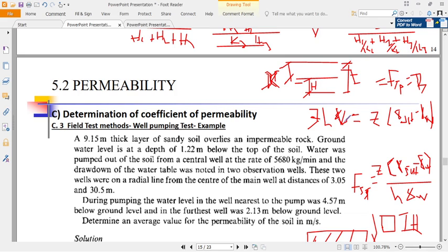There may be a pressure increase, should be equal to Z. Now, which is Z? Z is a function of X plus H. This H is the thickness of the layer which is known. So from there you can determine the amount of fill to put so that you reach a point of equilibrium. Now X will be the amount of fill to put here to prevent heaving or piping.